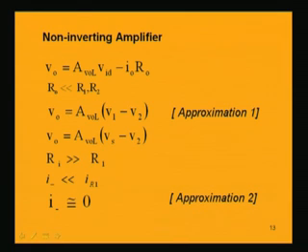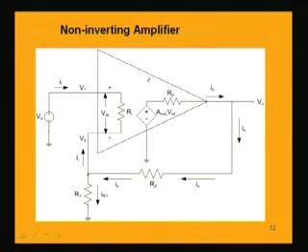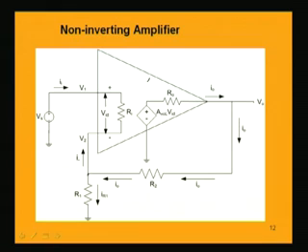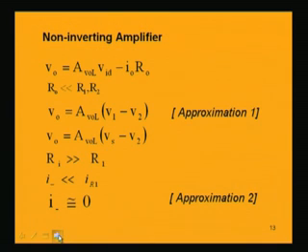So, V0 is equal to this. Now, here we will be making one approximation which is a valid approximation, we can cross verify also. The approximation is that this R0 resistance is very small as compared to R1 and R2. R1 and R2 are generally in the order of kilo ohms and R0 is only in the order of ohms. So, effectively this R0 is very small than R1 and R2. So, the drop I0 R0, this drop we will be neglecting here.